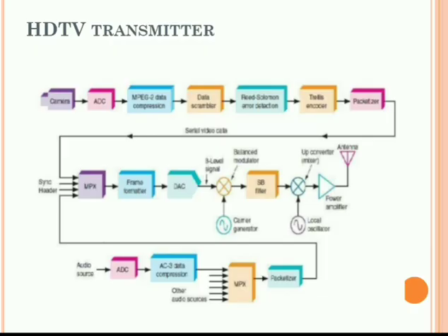After digitizing that signal, that is converting the analog signal into digital, we pass it through a compressor. We are using an MPEG2 compressor here for the purpose of compressing that data. The resulting signal is serialized and then sent to the data compressor. The purpose of this device is to reduce the number of bits needed to represent the video data, and therefore it permits a higher transmission rate in a limited bandwidth channel.